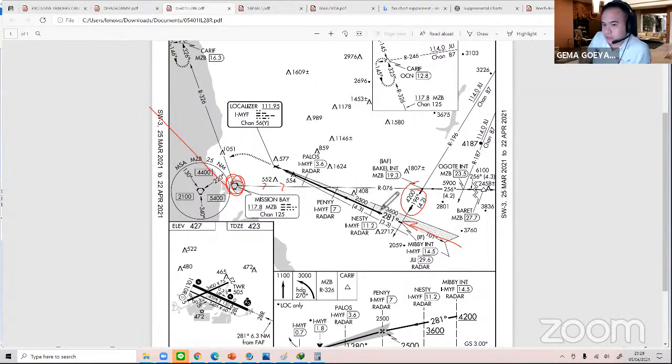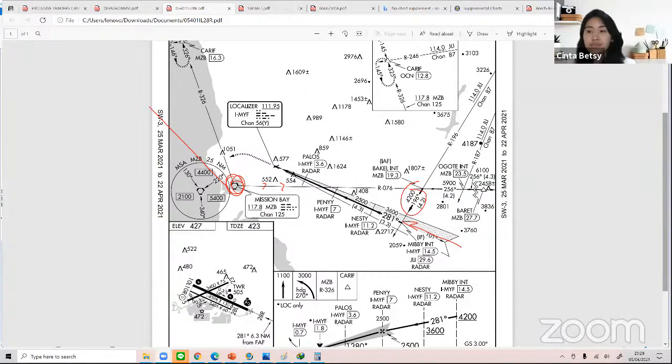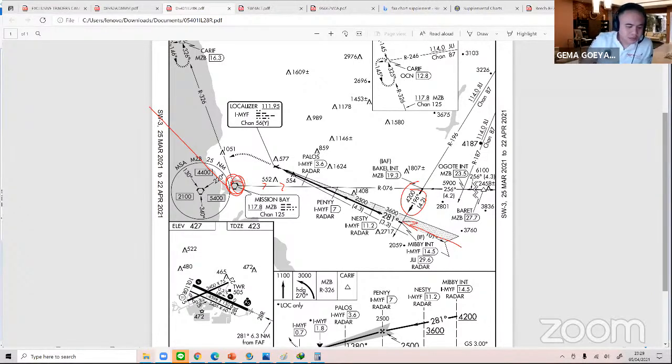But if your transponder fails, there's no way for them to know where you are for vectoring you, right? Right. So let's say you got a problem in the transponder, you got a burned transponder, you have to notify them, hey, I lost the Mode S transponder, then you have to find another airport that's friendly for you, especially when you got all IFR.